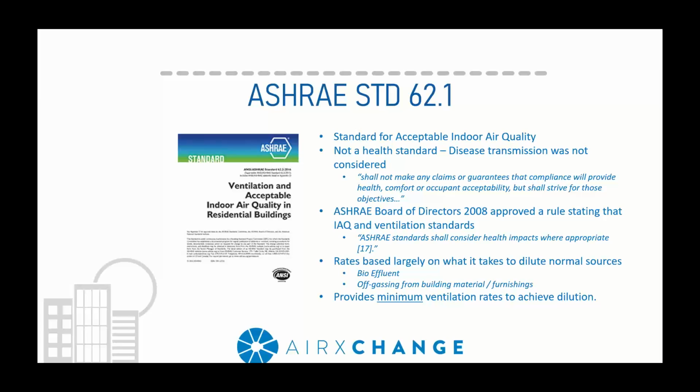But even with that in place, those rates that are within the standard are largely based on what it takes to dilute normal sources of contaminants. So what's a normal source of contaminant? It's typically bioeffluent, which is contaminants that come from people, more often referred to as odors, and off gassing from building materials, furnishings, or processes that may be occurring in the occupied space. And with those elements taken into consideration, the standard then provides the minimum ventilation rates to achieve proper dilution.